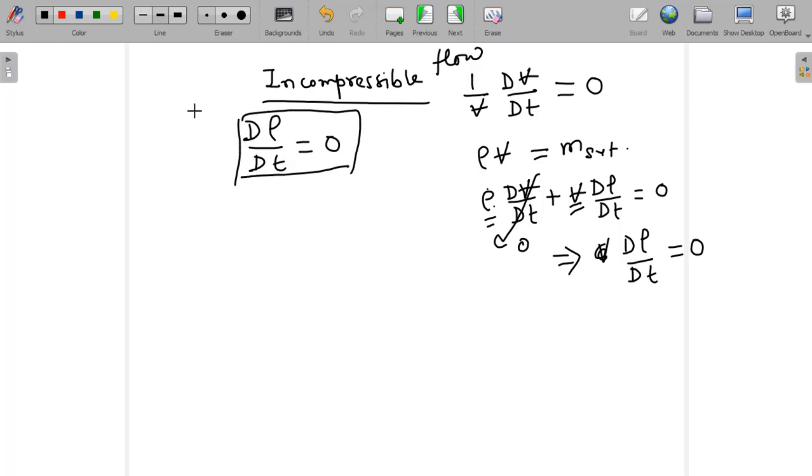So this is the definition of incompressible flow, we can write. See, this dρ/dt is the Lagrangian derivative. ∂ρ/∂t equal to 0, we cannot conclude if it is incompressible flow. Definitely if ∂ρ/∂t is 0, it will be incompressible, but if it is incompressible flow, we cannot surely tell that ∂ρ/∂t is 0, because ∂ρ/∂t is basically the density field variable partially differentiated with respect to time. So that quantity may not be 0. I am not going into much detail of this explanation. Maybe in the interactive session we may discuss it.